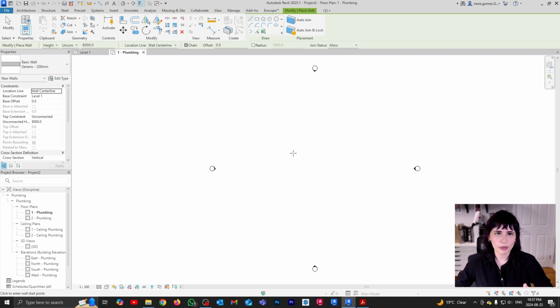So this is why it's so important to make sure that you choose the right template, because can I fix all of these things? Yes, you can change the unit system of your project. You can load assets from a different project or from other places to replace the ones that are in the incorrect unit system, or you can rewrite them and edit them. And you can edit the way that your views are organized and the number and type of views that you have. So all of these are fixable issues, but fixing all of these issues is a pain, so you don't want to go through it. So very important to make sure that you're choosing the correct template, okay?